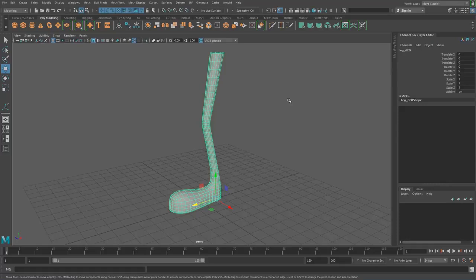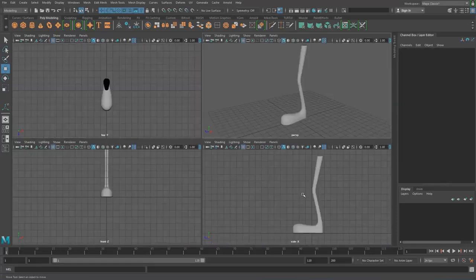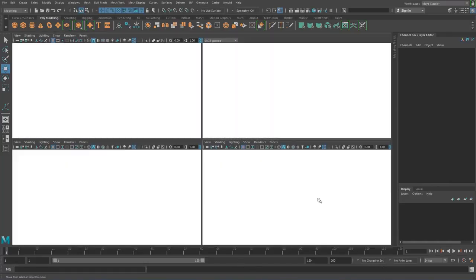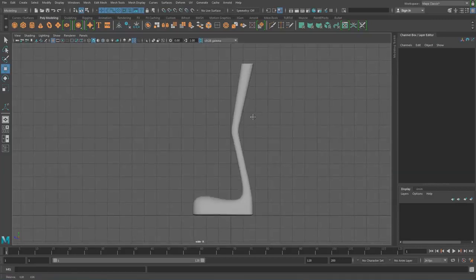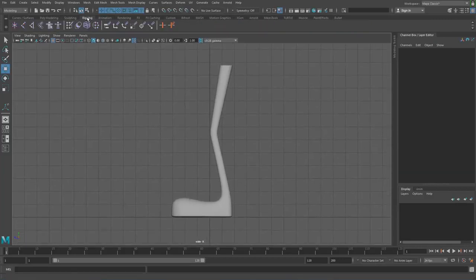So we're going to start by making a joint chain from the hip, knee, ankle, the ball of the foot, and then also the toes as well. So we're going to go into the side view, and the reason we do this is that it will then snap down this line of symmetry here. I'm going to go into Rigging, and pretty much everything I'm going to be doing here is under these two rigging tabs. So if you're within that at this point, you're pretty much set up for what I'm going to be doing. I'm going to go to the very first one here, the joints tool.